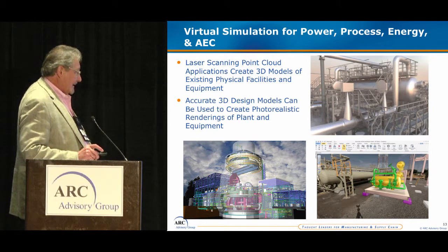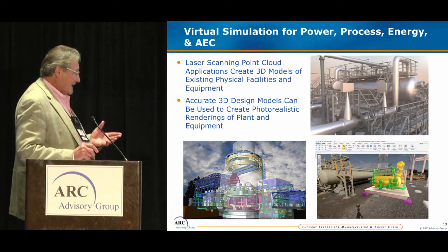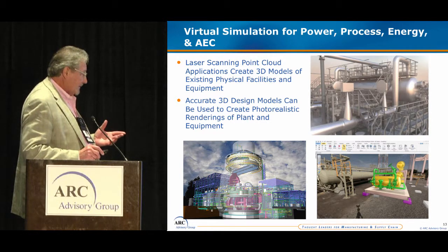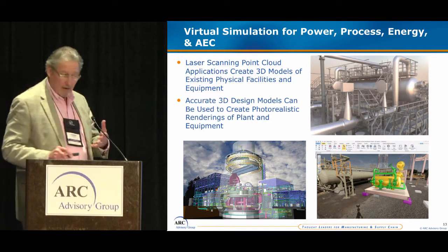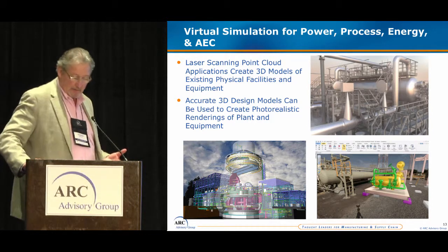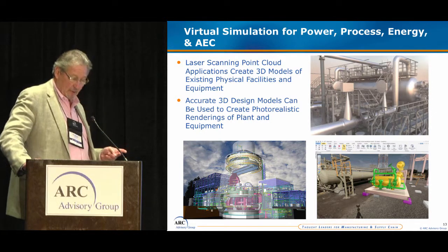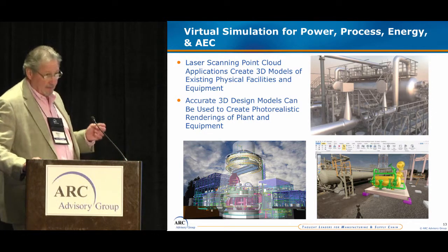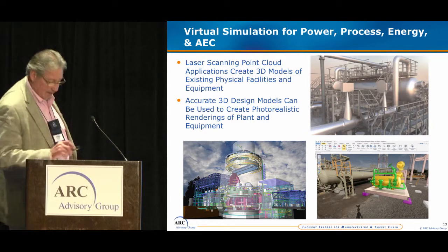Laser scanning, point cloud applications. Obviously, they've been out there for a while. They're really adding a lot of value to this entire process. You overlay the point cloud model over the actual design model. You can actually see differences and variations and so forth, and this helps immensely not only in brownfield, but it can also be applied to greenfield quite well.